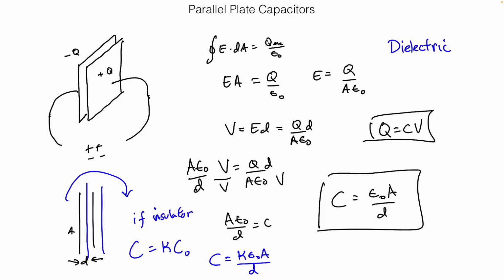Okay. All right, so we've got relationships with capacitance, its area. So what happens if we make the area of the plates bigger? What happens to the ability to store charge? Goes up, right? Because capacitance and area are directly related. What happens as we make the separation distance between the plates bigger? Ooh, it gets smaller. That's kind of interesting. So if we're trying to design a physical structure and we want to maximize capacitance, what do we do? Make plates as big as possible and get them as close to each other as possible, right?